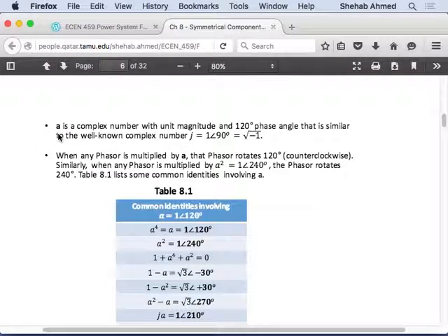But I typically want to know what the sequence quantities are, because if the zero sequence current is zero, what does that mean, based on our discussion earlier? If my zero sequence component is zero, what does that mean about neutral current? There is no neutral current, but the system is unbalanced because I have negative sequence.